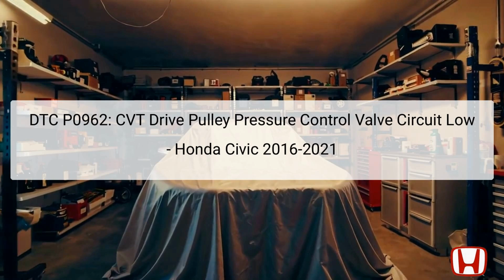The Diagnostic Trouble Code, DTC P0962, indicates an issue with the CVT, continuously variable transmission, drive pulley pressure control valve circuit. This problem arises from the valve's inability to maintain proper hydraulic pressure, essential for optimal transmission performance. The drive pulley pressure control solenoid valve plays a crucial role by regulating this hydraulic pressure based on electric signals received from the Transmission Control Module, TCM.